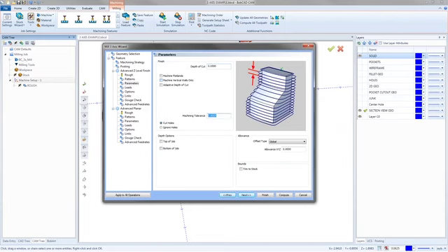So I usually leave the tolerance where it's at, do a decent depth of cut, enough that I can get an idea of how the finish is going to come out. And then when I'm ready to actually run it, I'll go change this to 10 thou, 20 thou, whatever I've got to do. And I'll do this to all of my toolpaths that need changes, and I won't compute them until they're all ready to be computed. And then I can right click on the milling job up at the top there and say compute all toolpath.